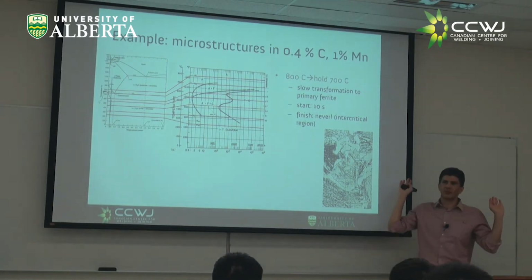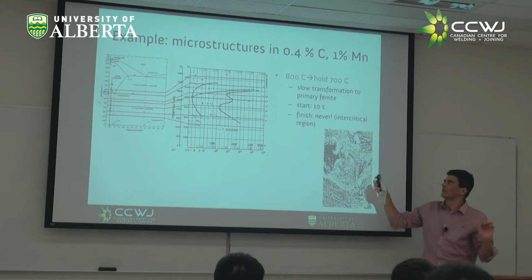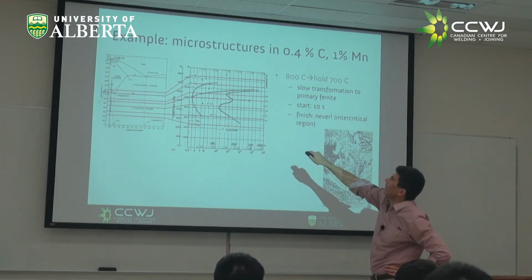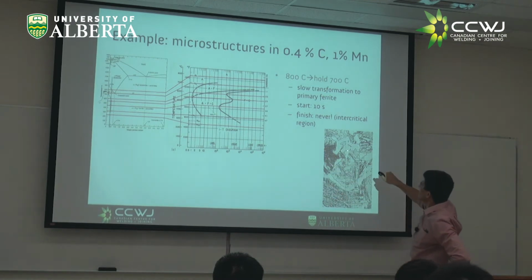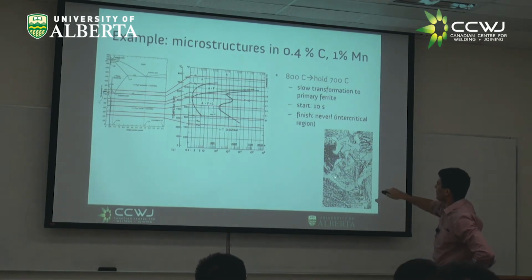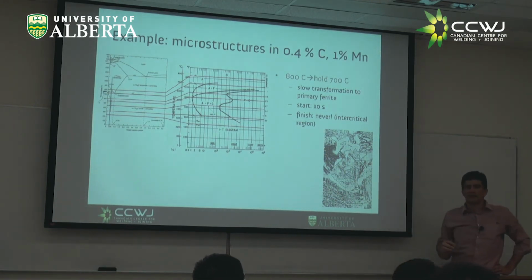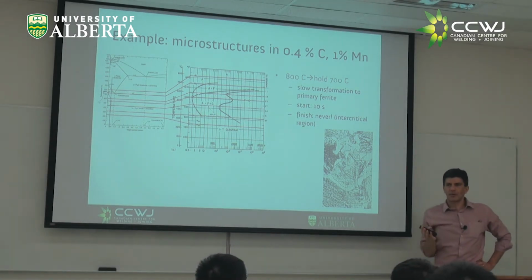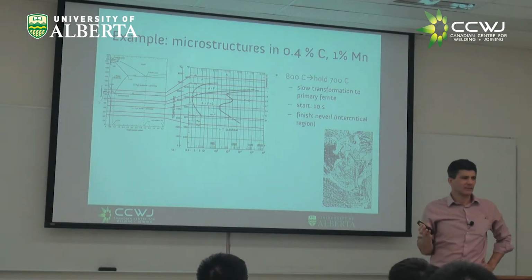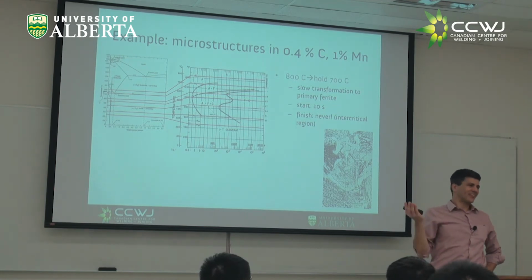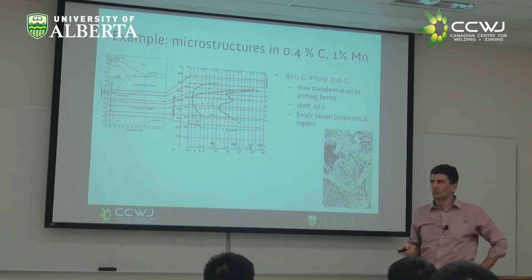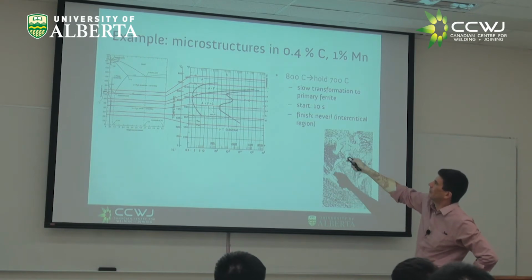Forever, it's living in a salt bath, right? Austenite plus primary ferrite. This is a primary ferrite, these things here. And who would remember where the primary ferrite tends to nucleate? Grain boundary, yeah, the standard answer, right? Yeah, that's where the primary ferrite typically nucleates.